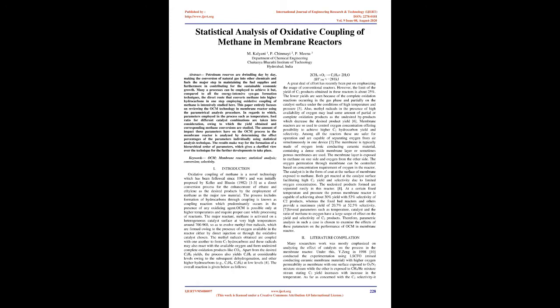The process includes formation of hydrocarbons through coupling, known as a coupling reaction, which predominantly occurs in the presence of an oxidizing agent. OCM is possible only at higher temperatures and requires proper care while processing the reactants. The major reactant, methane, is activated on a heterogeneous catalyst surface at very high temperatures, around 700 to 900,